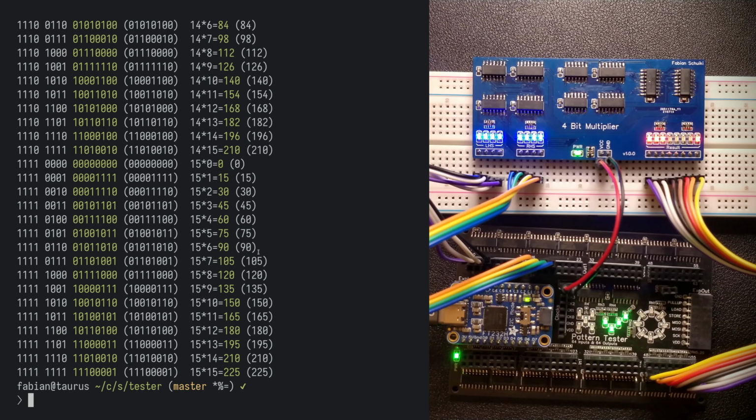And in this case, since this is a 4-bit multiplier, it's actually a complete and exhaustive test. We have tested every single piece of functionality. This is not going to be possible for hardware in general because the number of different combinations of inputs grows drastically as the number of inputs increases. And as soon as you have registers in the circuit, it becomes very complicated. But this is a good starting point.